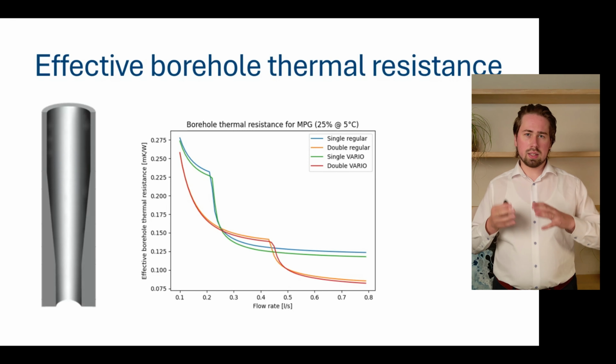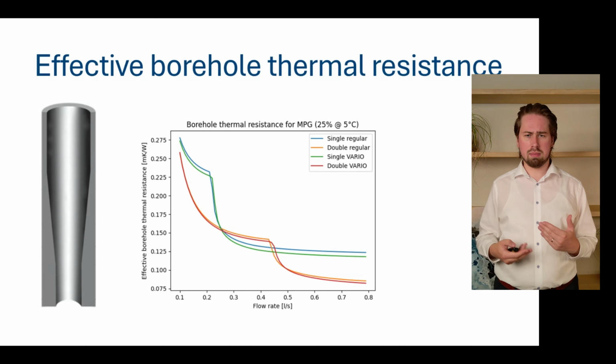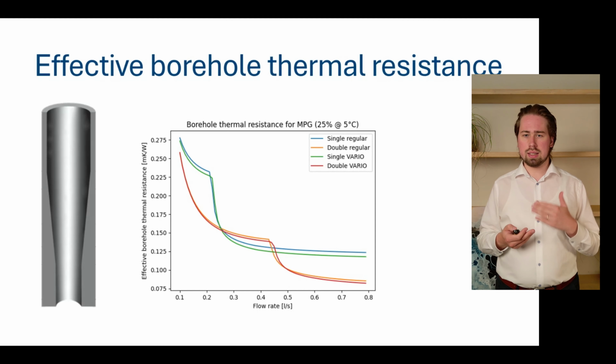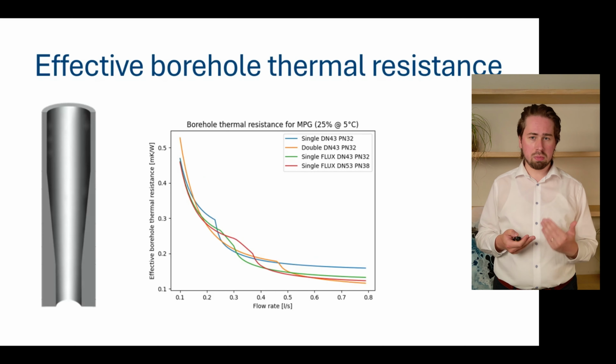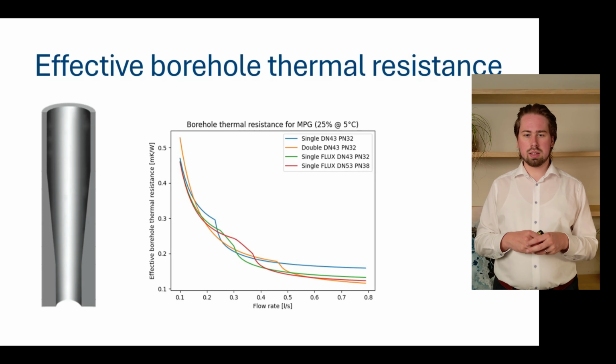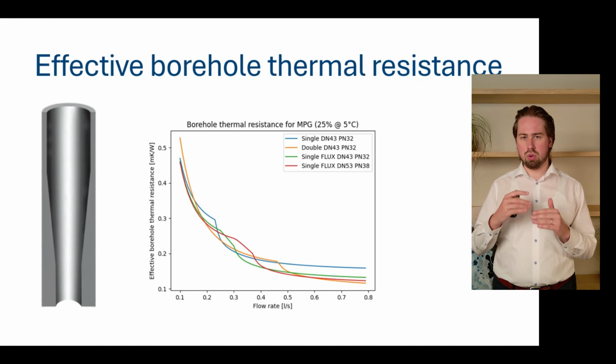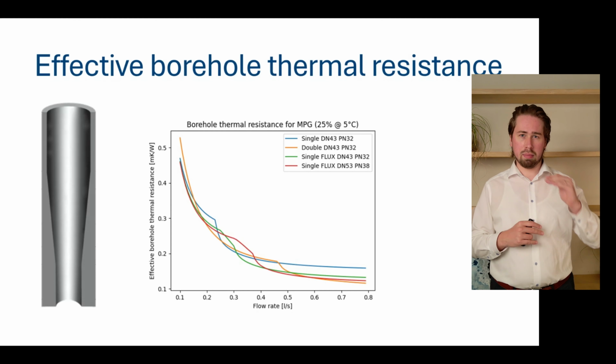Now, as said, these Vario and flux probes are actually designed with deeper boreholes in mind. So let us take a look at the case with a flux probe, actually at 350 meters deep now instead of 100. And what you see here is a very different graph. First of all, the effective borehole thermal resistance, the range is way bigger.